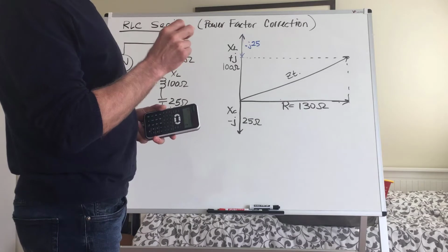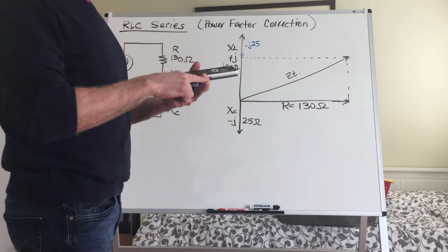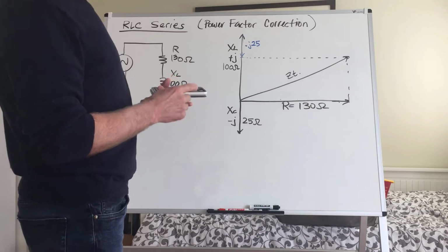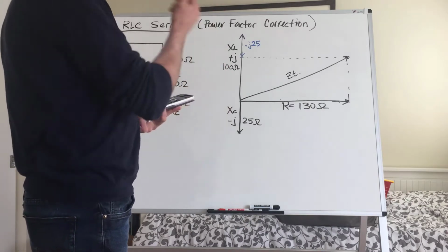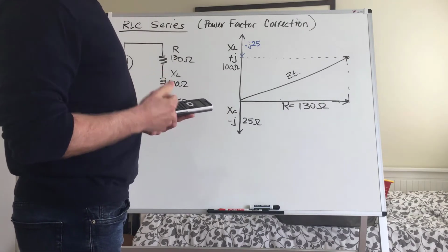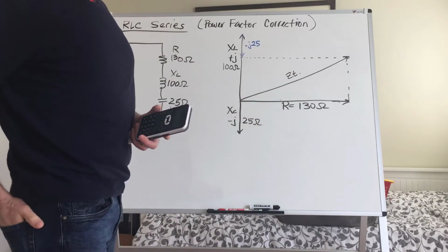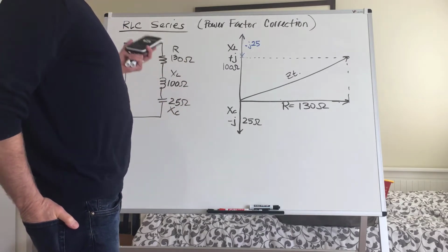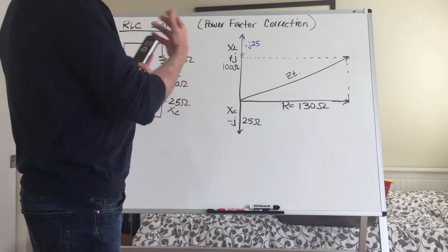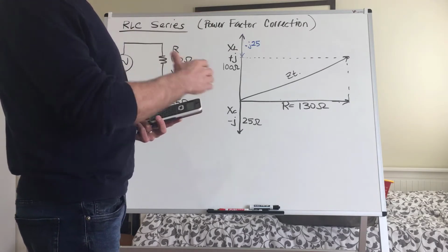that's really important because through the impedance triangle and your common current, it leads you into voltages for a voltage triangle and a power triangle when you look at the common current being squared and multiplying by each value of impedance to give you your power. When you look at the common current I total multiplied by each value of impedance to give you your voltage triangle, any RLC series circuit analysis should really start with the impedance triangle and using that total impedance to determine your current, and from there following through that process.